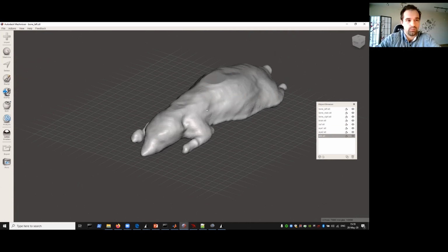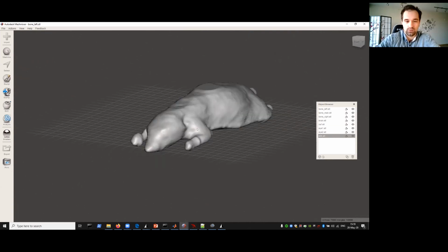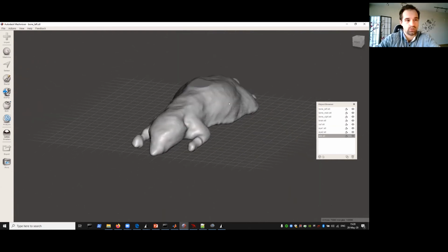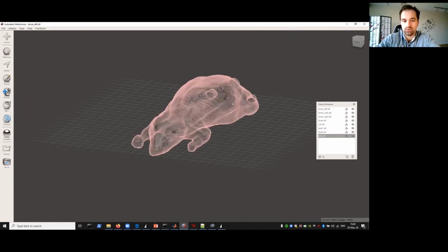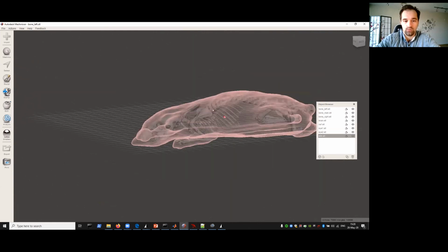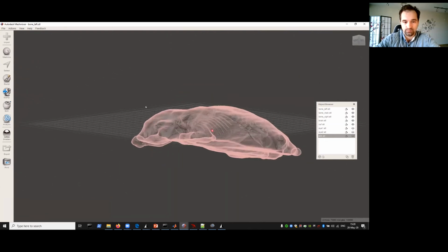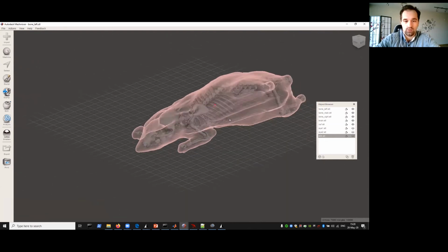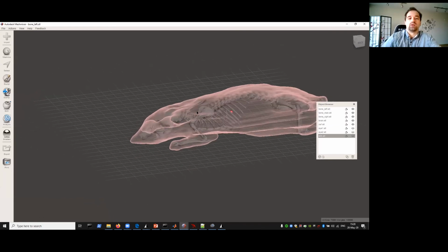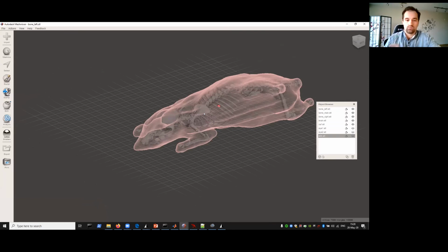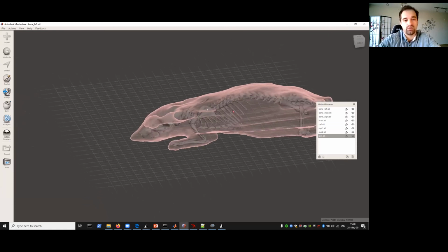I personally prefer the lineup of Autodesk, and right now on the screen you see the simplest of the Autodesk tools that I will show today, which is Meshmixer, that allows you to take a look at all the surfaces that you just generated after the segmentation, to see that they are accurately aligned, and to ensure that your surfaces, first of all, are enclosed, so there are no holes in the surface, so they're enclosed within each element.